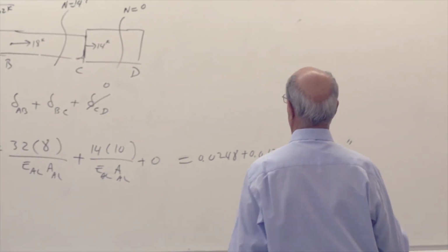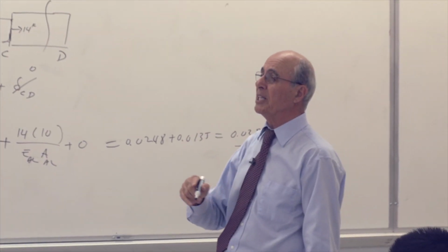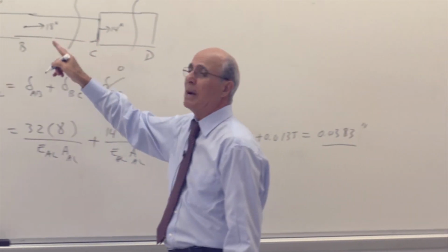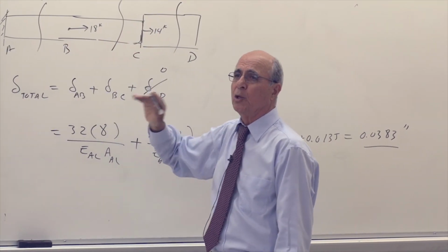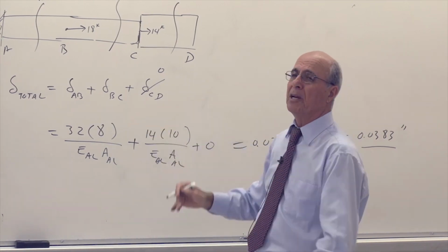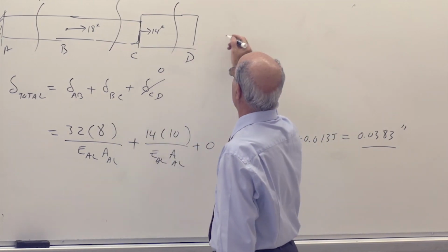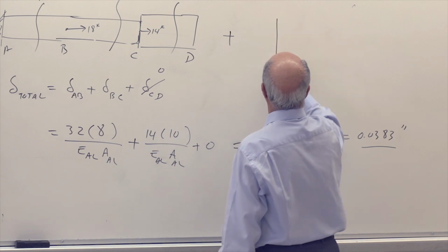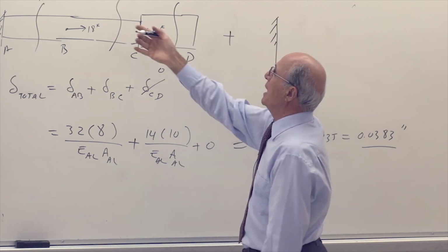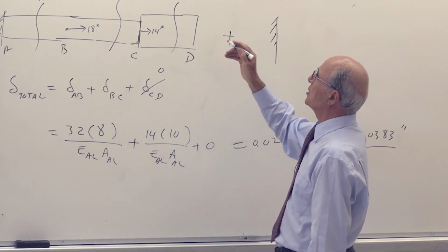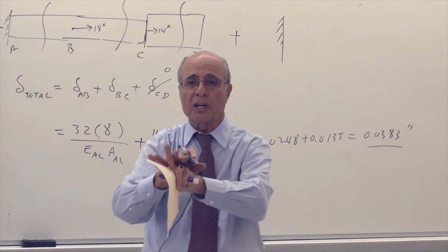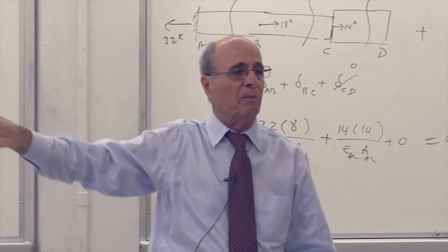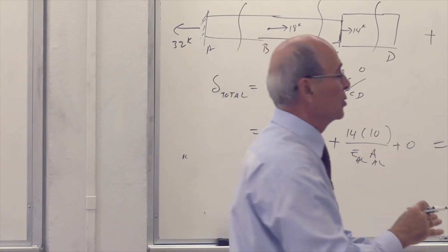In step 2, be careful here. Many people, when they do step 2, put this load back again. You should not put this load back again. Please make a note of that. The only force you have is the F, because this plus this system together is where the name superposition comes from. It means step 1 and step 2 should be superimposed on top of each other, so it becomes the original problem when they are added or superposed together.